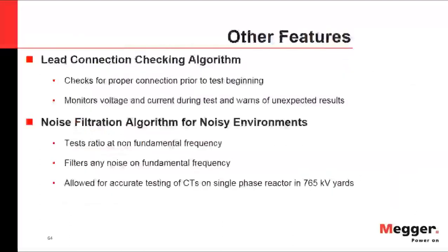Some other features that we have on the MRCT, we have the lead connection checking algorithm, which allows you to check for proper connection prior to test beginning. It will monitor the voltage and current during the test, and will give you a warning signal if unexpected results come up.